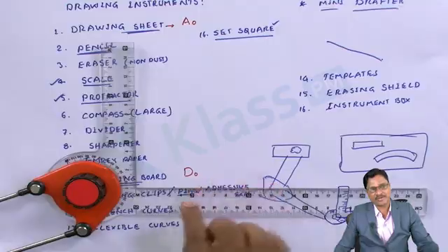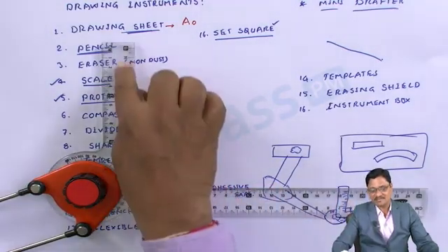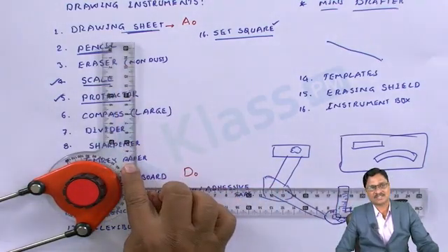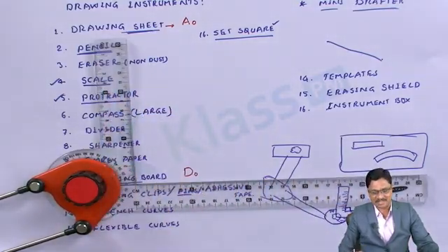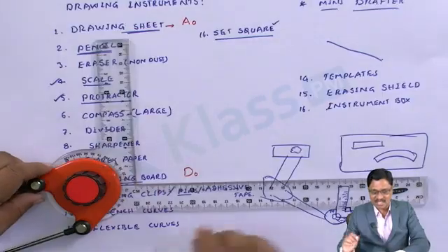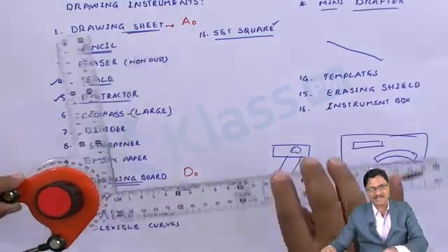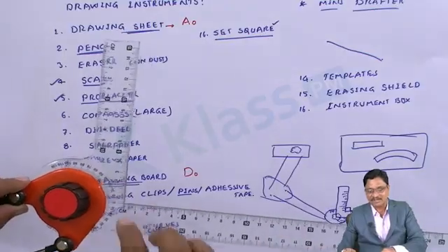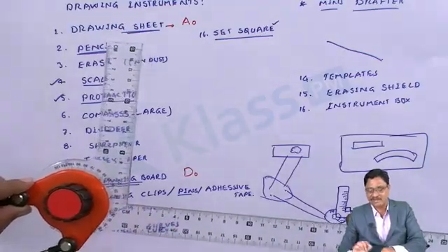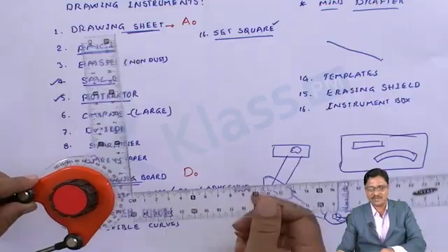Now what I told, the large scale as well as the small scale. This is horizontal in direction. This is vertical in direction. By this knob control, I can swivel here and there. How much I swivel is how much I rotated. By this graduation, I am able to measure this angle of rotation also.